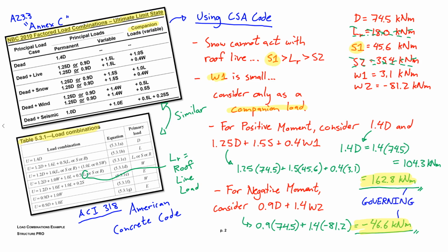That really wasn't that bad, was it? Don't be scared of load combinations. Use your brain. Don't go through the whole table one by one. Use your brain to eliminate possible cases so that you only have to investigate a few. And often you might have a hunch about which one's going to govern just based on the numbers. Stay tuned for some more concrete examples. Excuse the pun.